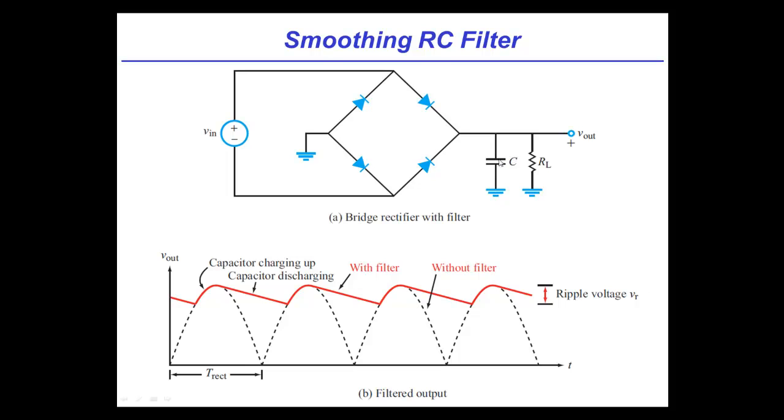So now what we're going to do is run this across a circuit that has a resistor in parallel with a capacitor and measure the voltage here. Okay, so think about this. Think about everything to the left of this point as almost a voltage source that produces this dashed line input. So this bumpy thing, half sinusoid.